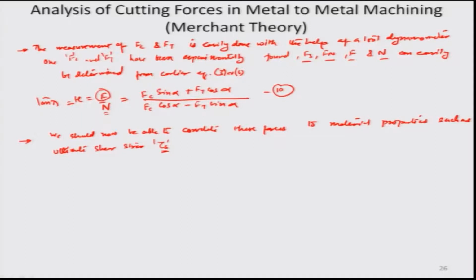The shear force Fs along the shear plane can be written as the amount of area of the cutting zone, which is actually the width of the workpiece times the uncut chip thickness T1.